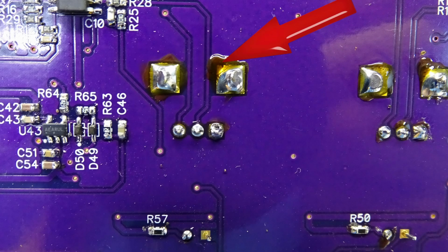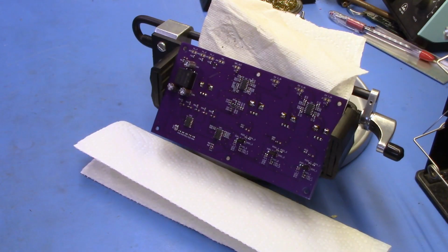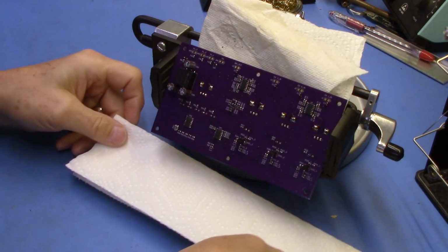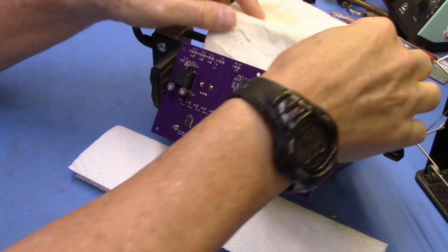Well, all of this soldering leaves flux residue all over the board. Ew, that's disgusting. And we don't want to leave that there. As I show in my soldering videos, we want to clean this stuff off of the board. My tool is this hardware store acid brush with its bristles cut real short. I place the board in a vertical orientation like this with several thicknesses of paper towel under it to catch the drips and the drizzles and the drool from the board.